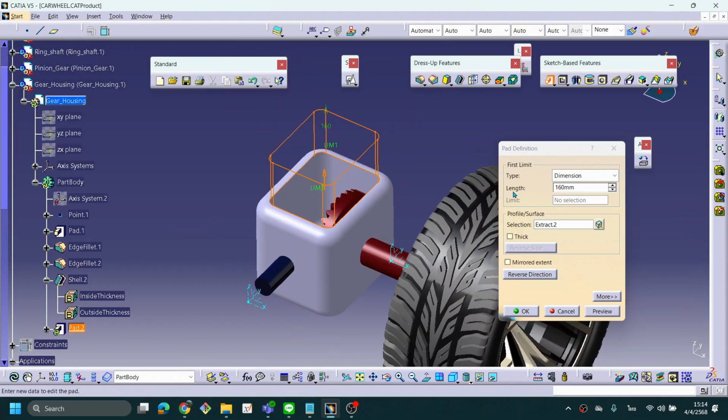This extract helps generate its curve for me. You don't need to select the sketch again. Create the rectangular block from a corner again. I use this because I already have the edges on the top part, since I did it about its edges before.